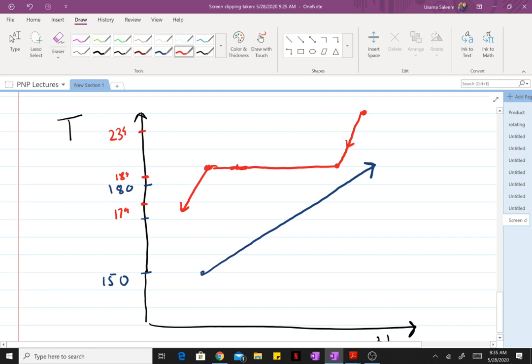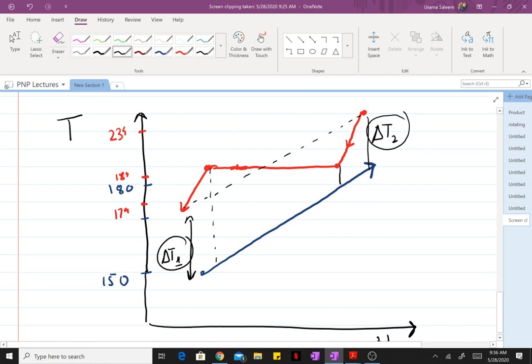So if you look at the countercurrent temperature profile, and if you were to use just the inlet temperature at one end and the outlet temperature at the other end, and took the log mean of those two temperatures, that would not work in this case, because you essentially have three sections of your heat exchanger. Taking the log mean of two temperatures only works if you have a smooth profile between both streams, which in this case is not the case. Therefore, instead of just giving up, what we can do is divide this heat exchanger into three sections.